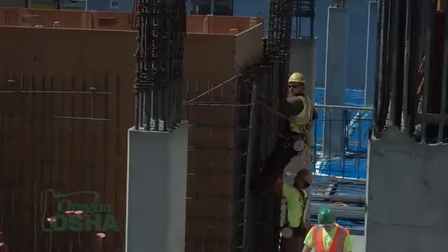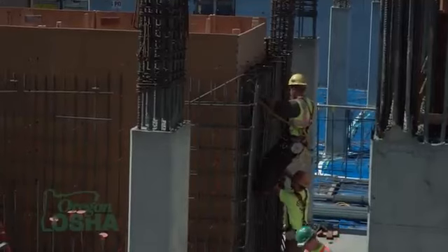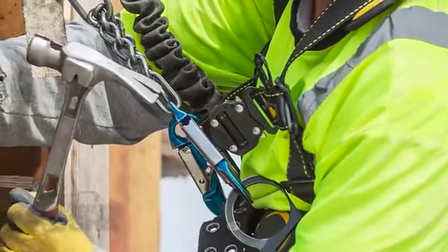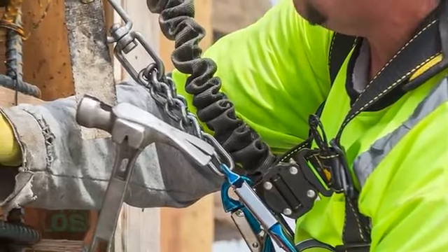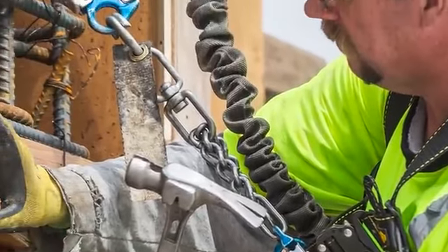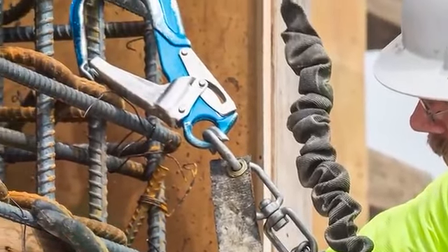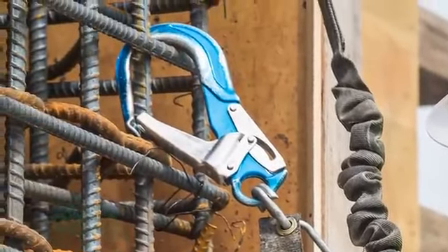A positioning device system is something that you use when you're working on a vertical system. For me, where I typically saw this used was ironworkers, people that were tying rebar on retaining walls or columns. The idea behind it is that they're typically two hook systems. This is so that the ironworker can climb up the wall, the structure, and basically hook off and then lean back into it. So it's always got weight on it when they're working. It's to keep them from falling, but it's also to give them an ability to use both hands while they're working.